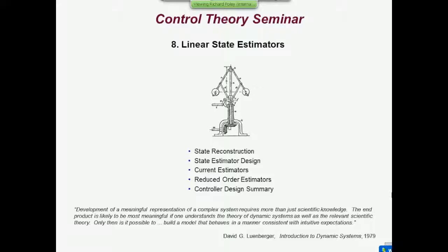And then I'm going to talk about how you produce a linear state estimator, how you design it, and how it produces the state vector for us. And this will lead us, hopefully, in a series of intuitive steps to a design of estimator known as a prediction estimator. It'll produce the state vector for us, but the method that it uses to do it uses an output measurement which is one sample out of date. Or seen another way, you're predicting the state one sample in advance of the most recent measurement you've got.